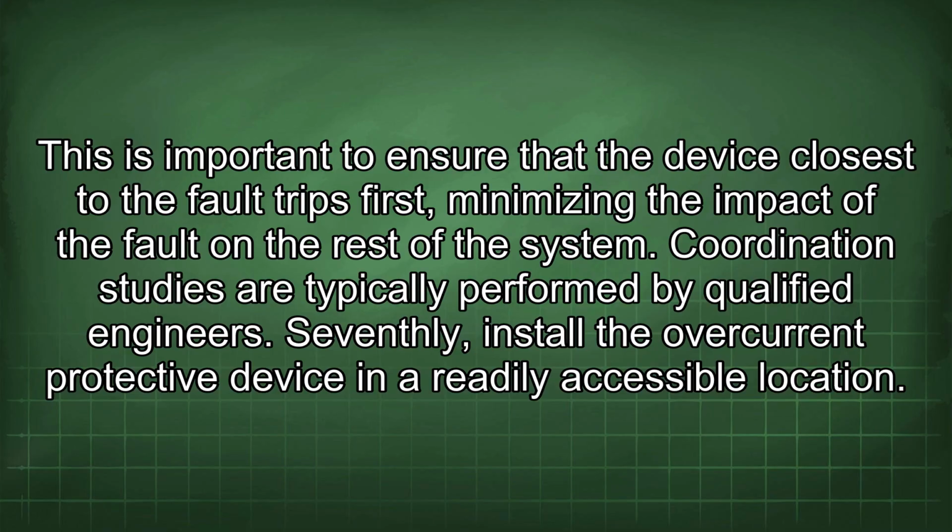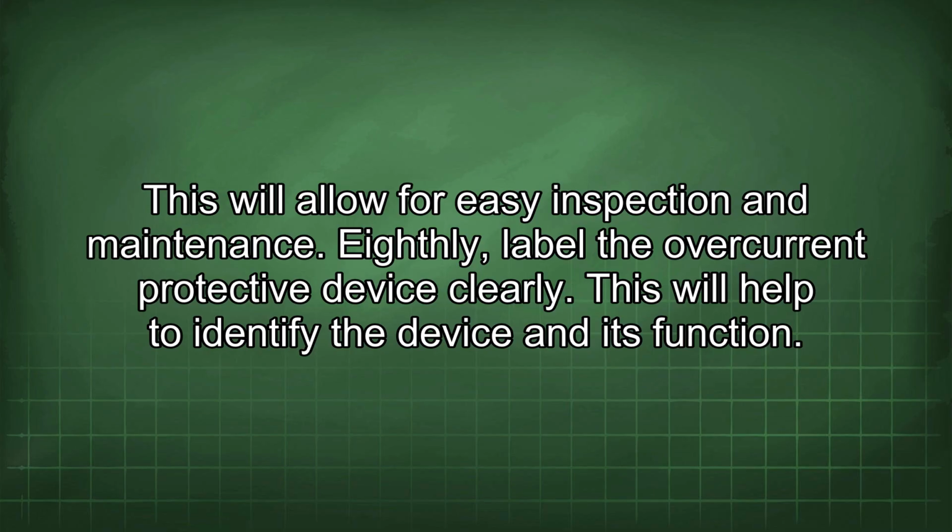Coordination studies are typically performed by qualified engineers. Seventhly, install the overcurrent protective device in a readily accessible location. This will allow for easy inspection and maintenance. Eighthly, label the overcurrent protective device clearly. This will help to identify the device and its function.